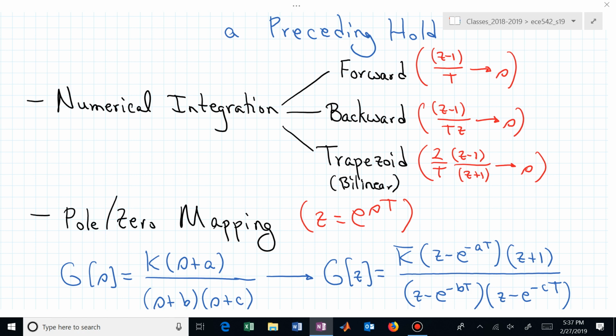If you looked at this ratio as s goes to infinity, then you really look at s over s squared as s gets big, and that now looks like a 1 over s, so you have 1 zero at infinity. If s goes off to infinity, this g of s expression vanishes. If we just had k in the numerator, then we would have 2 zeros at infinity.